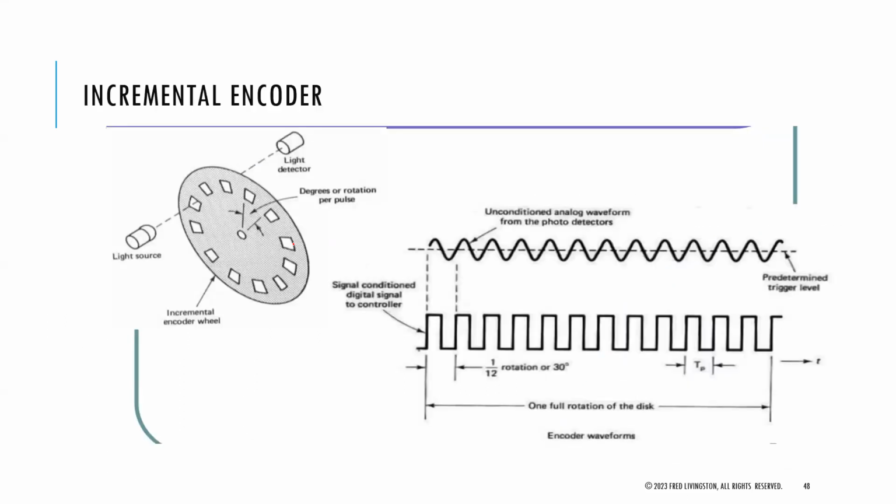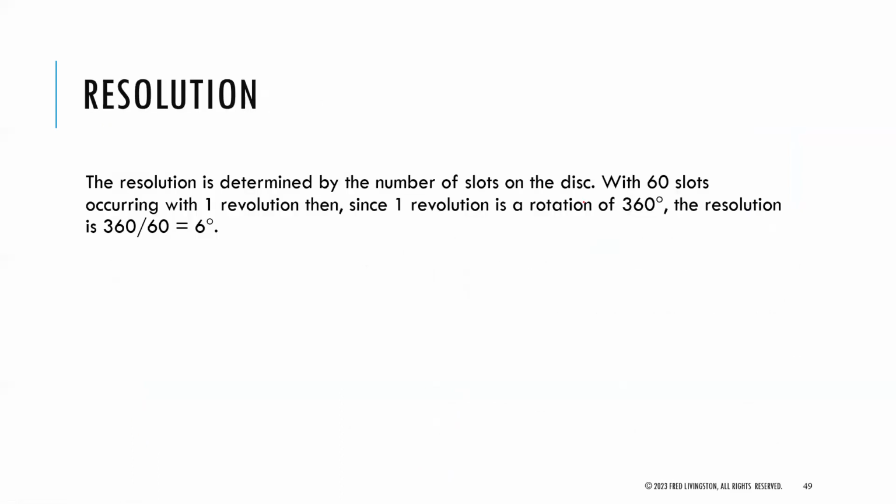And then we also talked about encoders. As the light goes through, it's going to block the light or let the light pass, giving some kind of pulse. And you'll be able to count the number of pulses, given the radius of the disc. This goes into linear actuators, for those using conveyor belts for their project. If I want the conveyor belt to go to X distance and it has an encoder there, I could count the number of ticks, and that's equal to a certain amount of distance in your system. So given the encoder size, the disk size, and the finer resolution of the system.